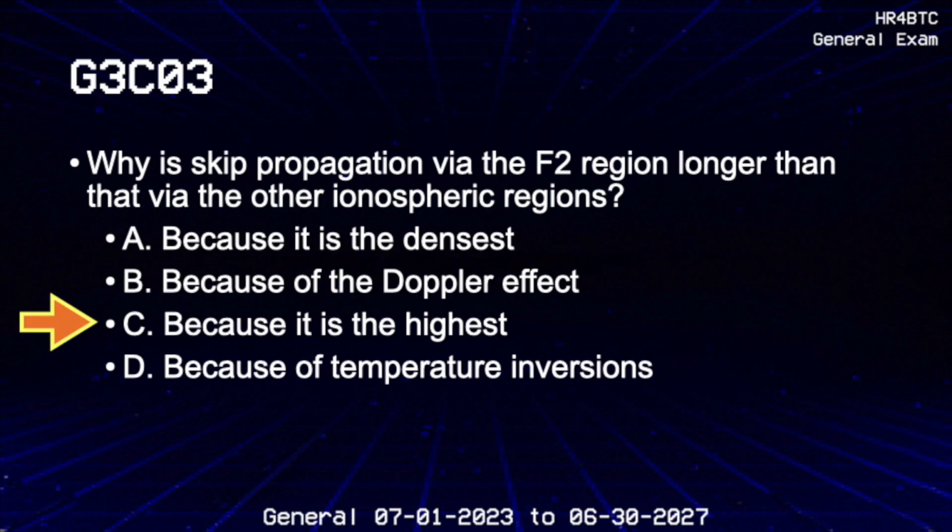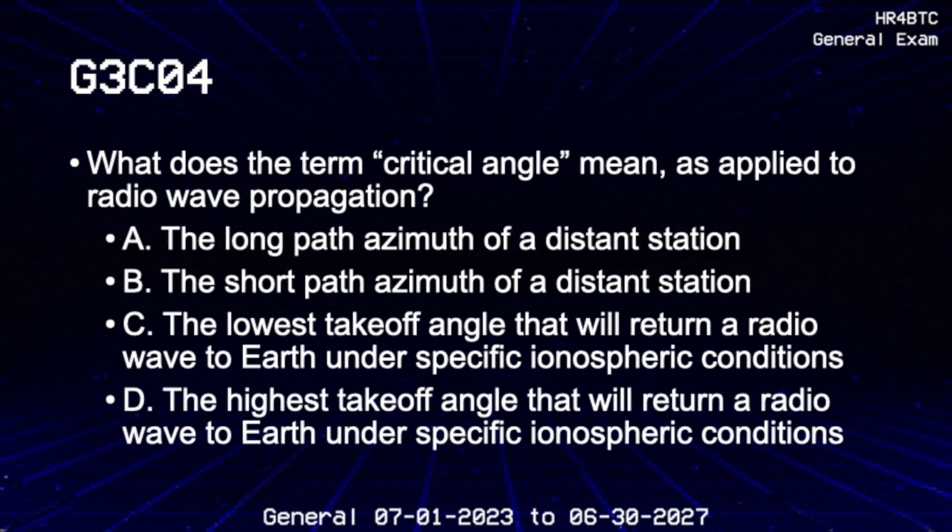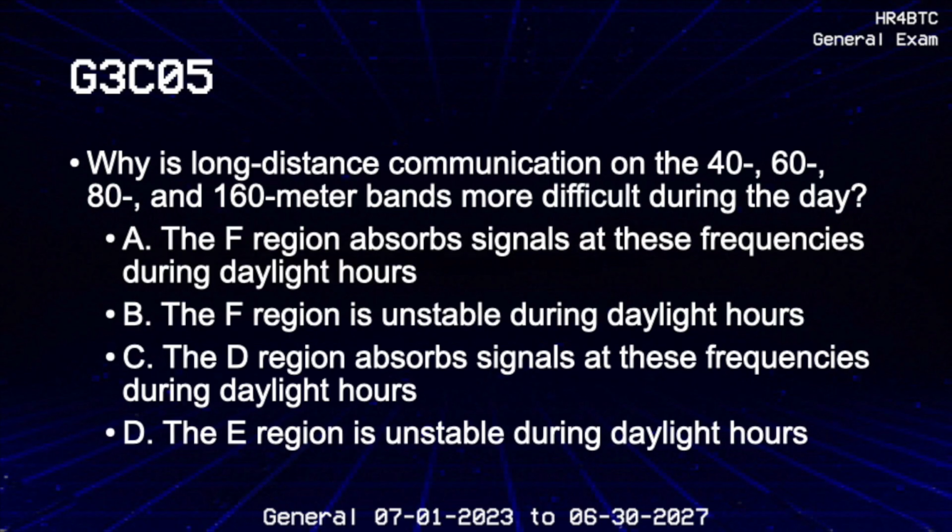Because it is the highest. What does the term critical angle mean as applied to radio wave propagation? The highest takeoff angle that will return a radio wave to Earth under specific ionospheric conditions. Why is long-distance communication on the 40, 60, 80, and 160-meter bands more difficult during the day? The D region absorbs signals at these frequencies during daylight hours.